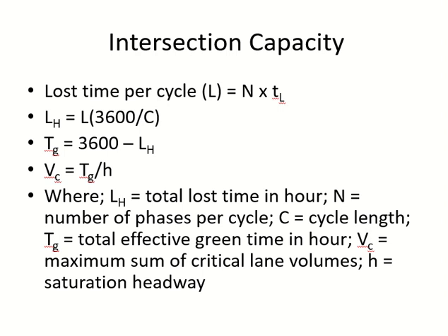When you are standing at a signal, it's not green for you every time, right? So you receive a portion of the total time for your movement. That portion is called a phase. Green plus yellow plus something else. Clear? So whenever the signal has a phase, it has a loss time as well.